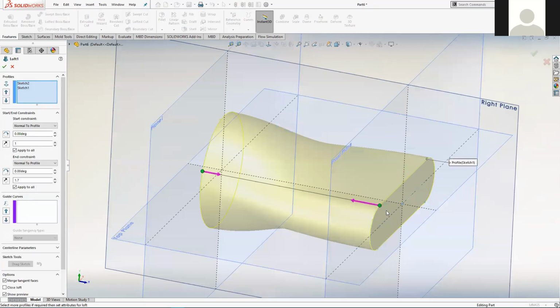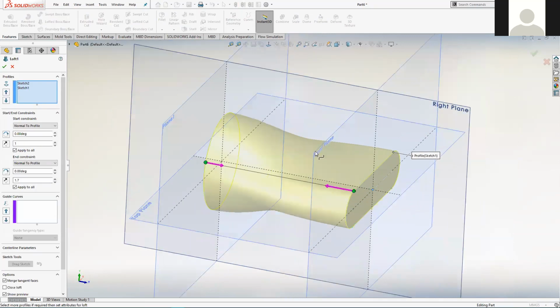Now, the one thing that we haven't covered in this example that we may return to, and we'll cover it a bit later on, is that a loft doesn't just have to be a transition between two sketch shapes. This box will accept as many sketches as you want to create. So yeah, we'll revisit this and we'll create a loft that's got 3 sketches. But again, that's not even the limit.